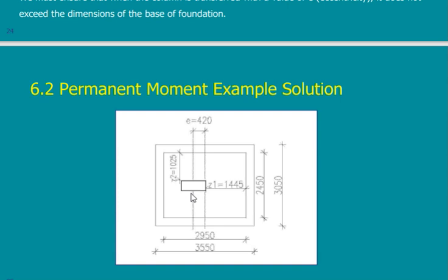If I take this CG down here, what I'm doing? I am doing another eccentricity in the opposite direction. So if the original CG of the column was here, I shifted this CG this direction. When I shifted it this direction, I induced a moment opposite to the X direction. So suppose I take it from here and go down, then it is double eccentricity: eccentricity in the X and eccentricity in the Y. So if I give you two moments, the answer will be also the same. The difference will be in the location of the column.